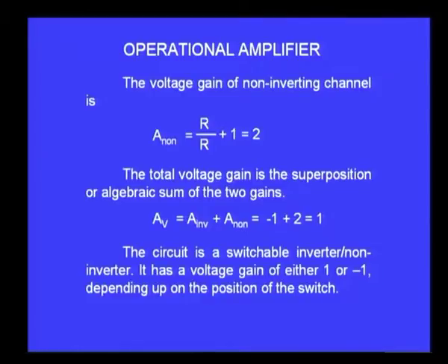So, it will be sometimes very useful in different applications, and therefore, I wanted to discuss this. Now, what I will do is quickly show you the same circuit wired on the breadboard, and I will show you how this can be very easily switched. Instead of using a switch, I will use one single wire which is connected to the non-inverting terminal. I will either connect it to ground or to the input of the inverting terminal. Thereby, I will show you what happens to the gain at the output.